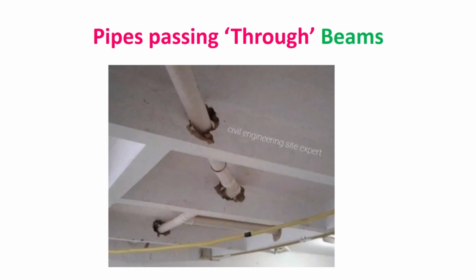Are you able to understand? Now there may be cases many times. I will tell you my example. We were doing a building activity, and the foundation was at around 4 meters or 3 meters. Now the designer has assumed that particular strata as muram or soft rock or whatever the strata is, with no groundwater near it. Now when I was executing that particular work, we found that there is groundwater at that particular depth of 3 meters.